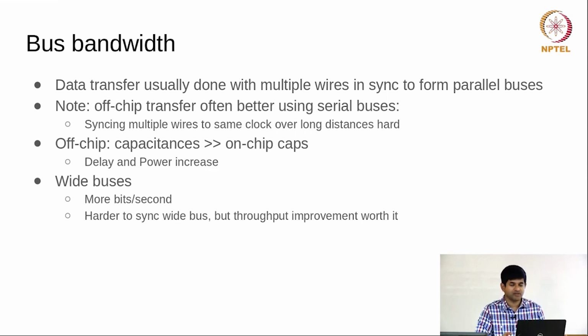Wide buses at the end of the day are always good in the sense that you can transfer more data per clock cycle, which translates into more data per second. But it's harder to synchronize wide buses. So they are used only in specific cases where you exactly want that high bandwidth, high throughput kind of communication.